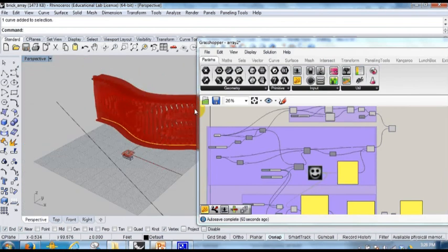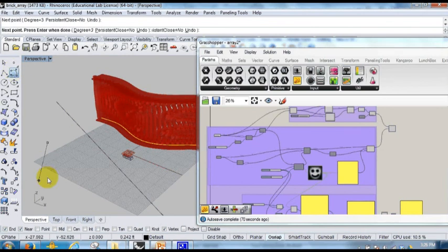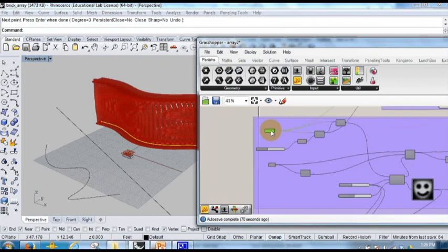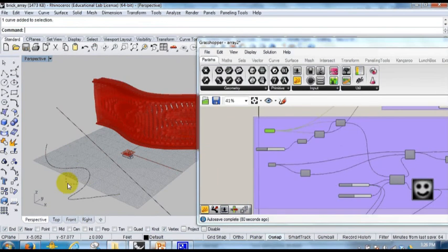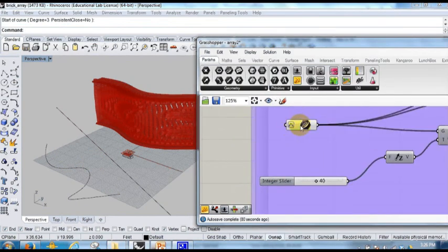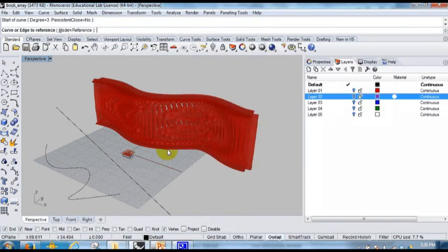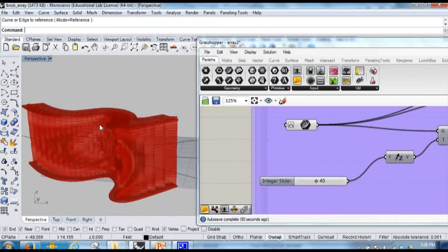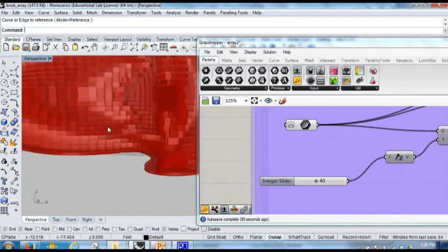One is the curve itself, whether a straight line or a curve. You can define a curve. If I build up a new curve, I can just simply set it to the new curve. So the wall will update, the roof will update, the base will update.